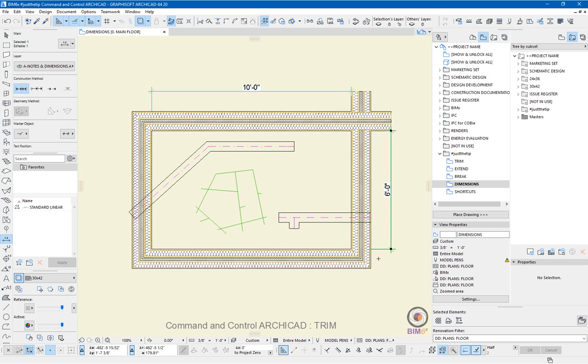and maybe what I want to do is add the corners. So we're going to hold down Control, we're going to look for a tick mark, make sure we've got highlight so it's going to associate, click the mouse, and there we go, Control click, and that's just added additional points. If I want to add a point that's in the middle, it's a bit like break, then Control click, and that adds that one. Control click in here, and that adds that one. And you can literally Control click anywhere. So that's a non-associative point because it's just a random point in the middle of nowhere.